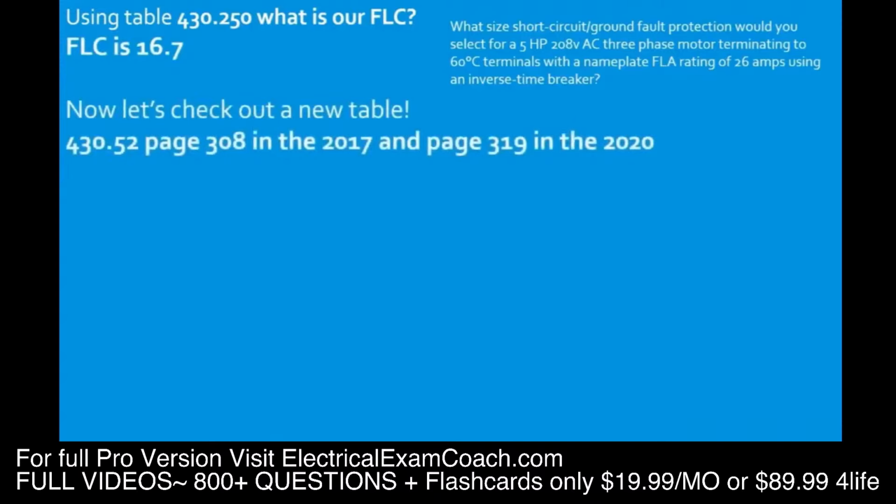So everyone head to 430.52, page 308 in the 2017, and page 319 in the 2020. When we get there, the first thing that we do is we read our black bold heading. It says maximum rating or setting for motor branch circuit, short circuit, ground fault protected devices. I feel like we're in the right place. Now on the left-hand side is going to be your type of motor, whether single phase or polyphase. Then across the top, you're going to notice different types of devices. There's a non-time delay fuse, a dual element fuse, an instantaneous trip breaker, and an inverse time breaker, which is the breakers that we normally use.